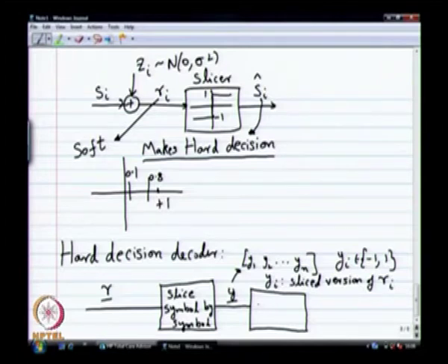How do you do that? You do inverse BPSK. You can write an expression if you like for inverse BPSK, which will be (1 minus y) by 2. So that is the inverse BPSK. Let us say you get a w. Now remember w now is n bits. So at this point you can run your syndrome decoder.